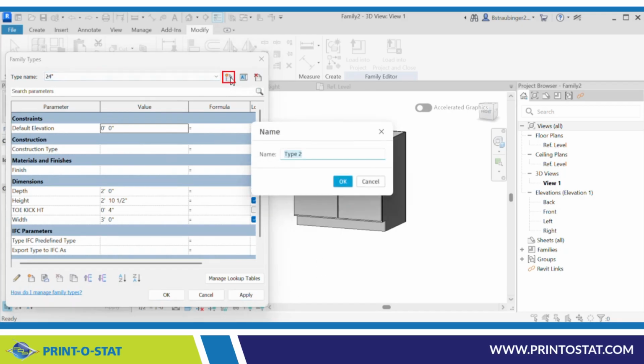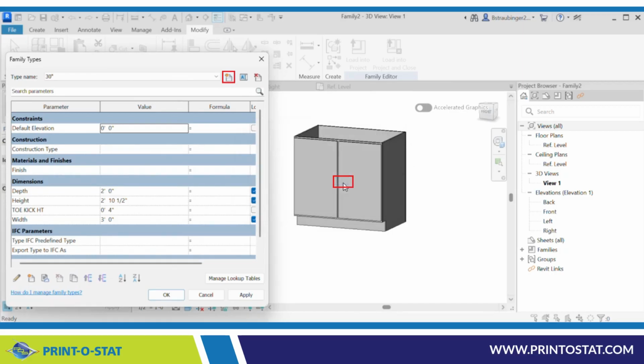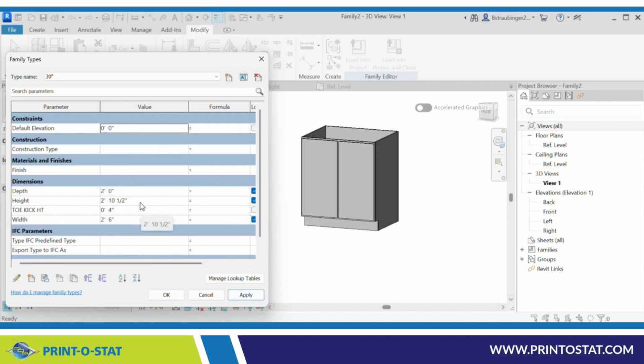Now I'm going to do it again. I'm going to call it 30 inch. Hit apply. I'm going to change the depth, change the width to 2'6", 30 inches. I hit apply so that it associates these dimensions to this type. It will flex and move as it does that. Why is the cabinet 2'10.5"? Because once you put the 1.5 inches of countertop on top, the counter's at 3 feet, which is a standard.